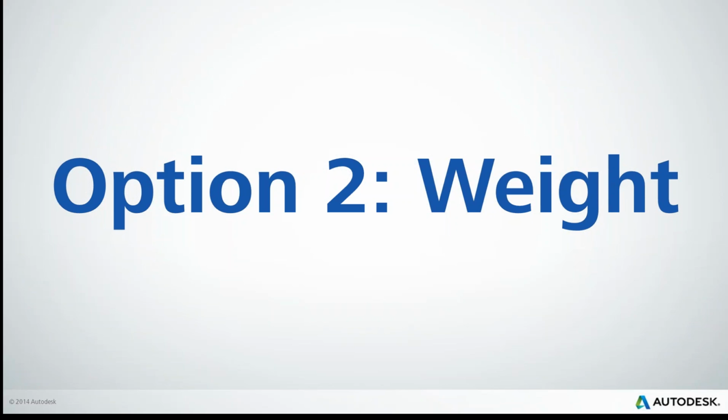So if you're just doing a linear stress analysis, a force is actually a little simpler and easier to use, and there's no reason why you shouldn't use it. But once you get into modal, the vibration type of analysis, you're going to see that you really don't want to be using a force. Yeah.